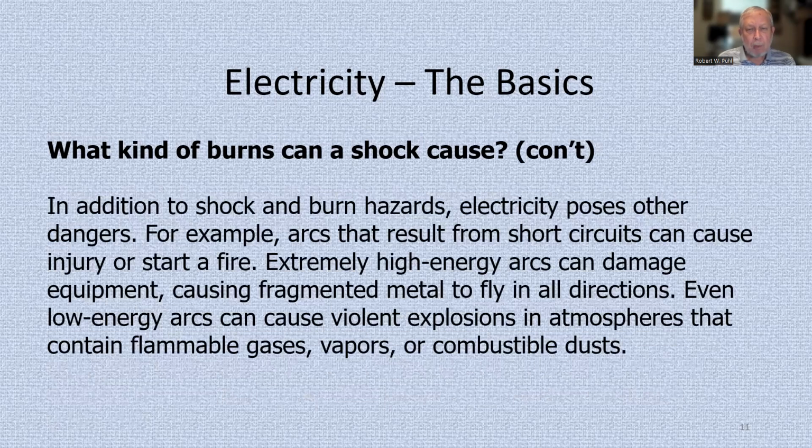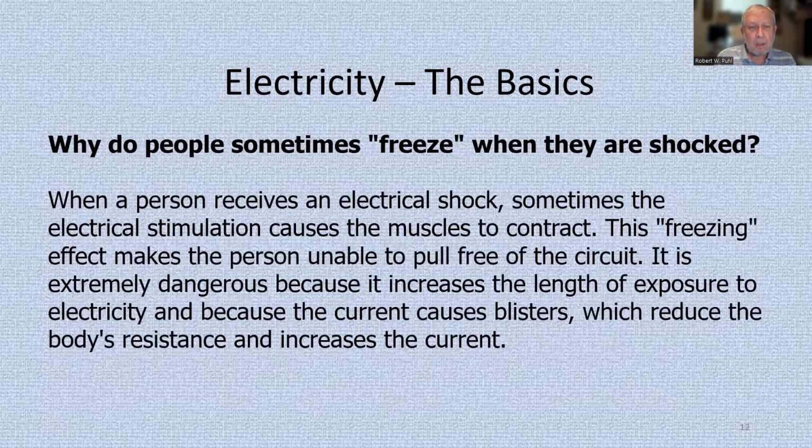In addition to shock and burn hazards, electricity poses other dangers. For example, arcs that result from short circuits can cause injury or start a fire. Extremely high energy arcs can damage equipment, causing fragmented metal to fly in all directions. Even low energy arcs can cause violent explosions in atmospheres that contain flammable gases, vapors, or combustible dusts.